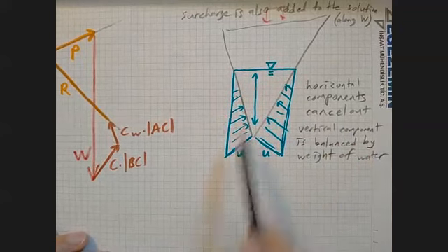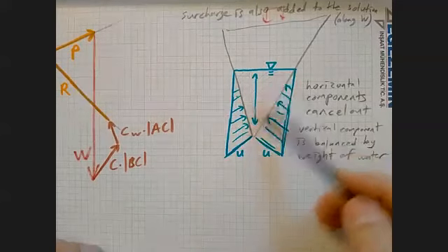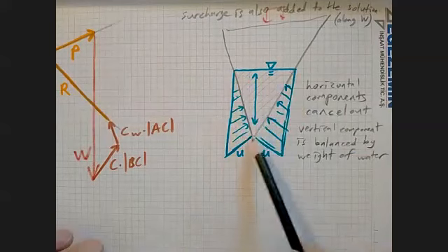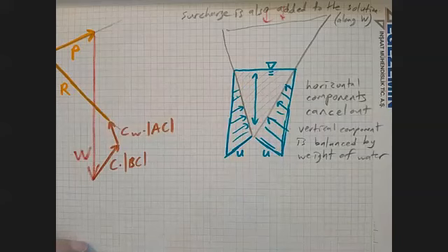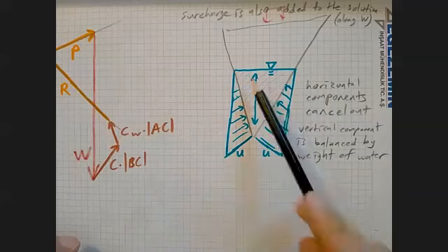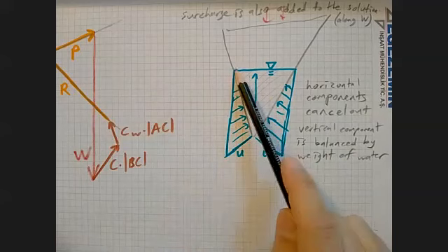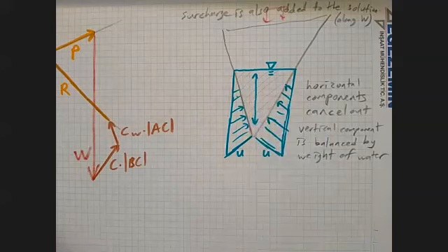But not the weight of the water in the soil, it is the weight of nothing but water in this V-shaped container, as if there is no soil, it's just water. Right, that's familiar. So my water forces are upwards and they have the same weight as this volume of water.